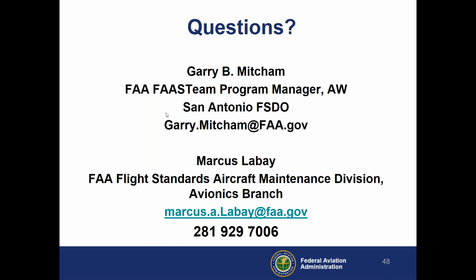The next question is, can we speak to STC installations? The asker has left the presentation, but basically, as far as an STC installation, what I was talking about there was every STC has instructions for continued airworthiness. So those need to be followed. And if you find that they're not adequate to prevent false targets, then I would contact the STC holder and have them update their ICA.